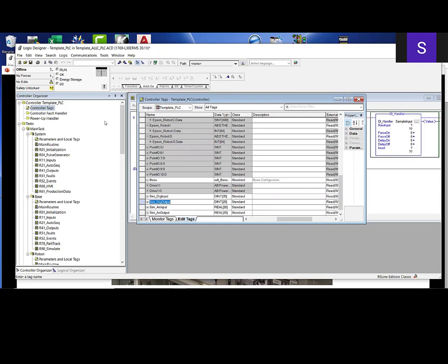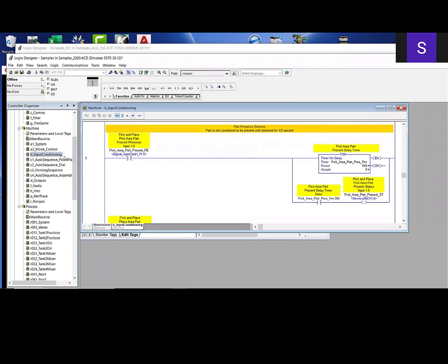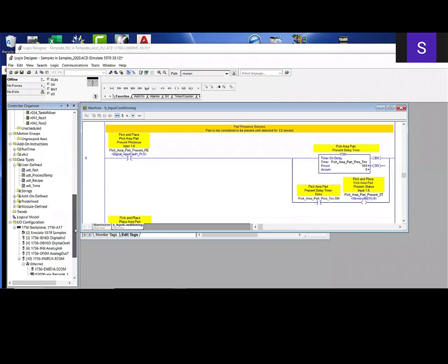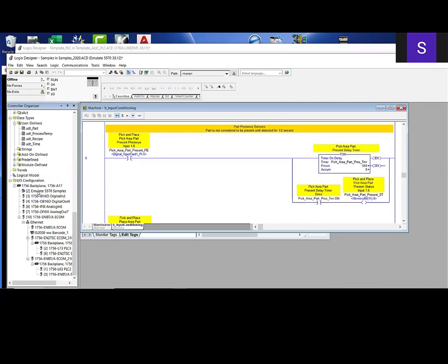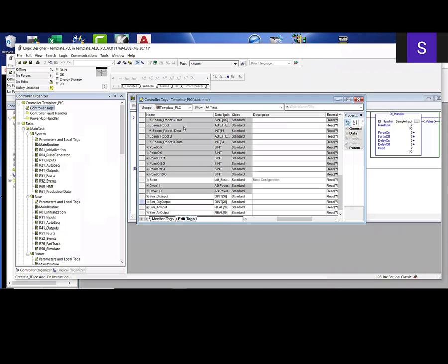right? Template PLC, and I'll have to reconfigure this. This won't be this safety PLC anymore. It'll have to be configured as a simulator. So here's an example of that. This was the sample program I showed you before. If I go to the hardware down here, it says emulate 5570 samples, right? So it's a different processor and it's got physical cards with it and everything. And I can download this straight into the emulator. That's it. It says up here, emulate 5570. So this one here, because it's a template, will not be configured as a simulator. What I'll do is I'll save the template.